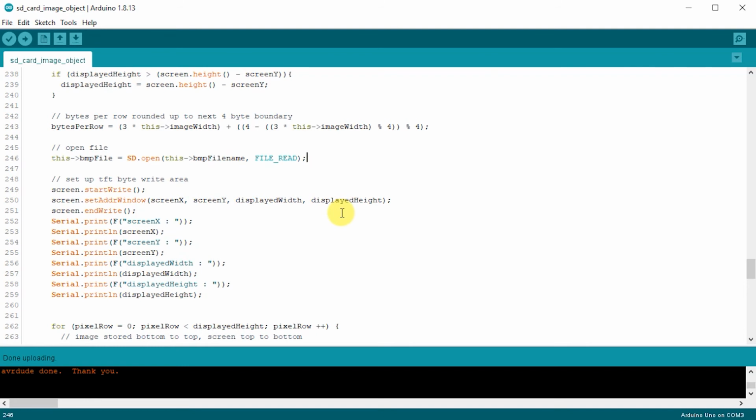All we have to do is start sending pixel color data out, and our LCD screen will take the area that we've set as the active area and start filling it from this top left corner position. It will fill the top row of pixels first, and we just keep sending it pixel information until it fills up that whole target area.